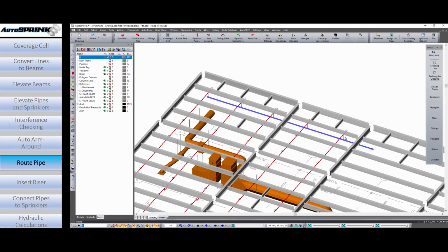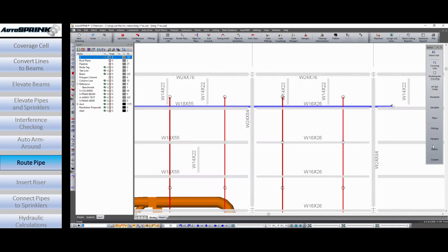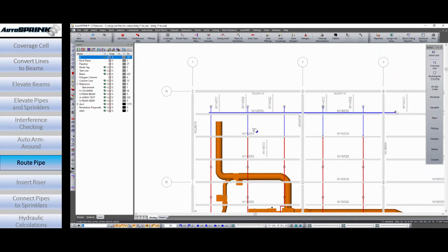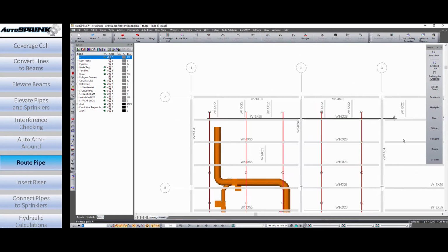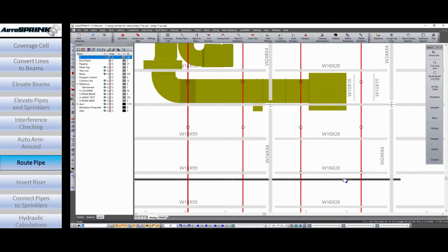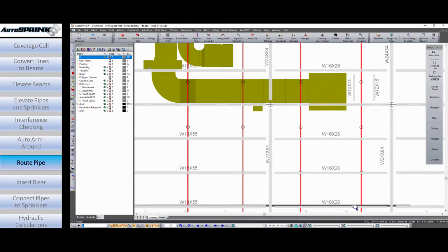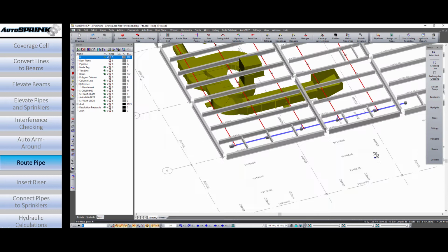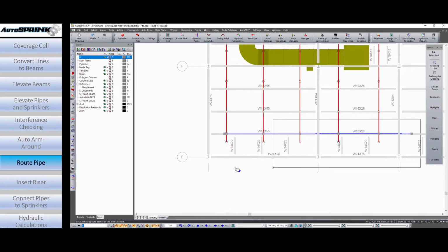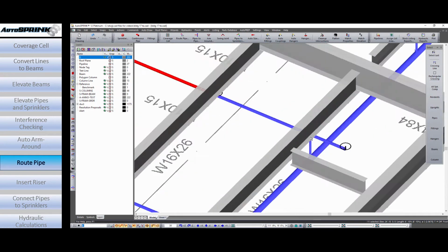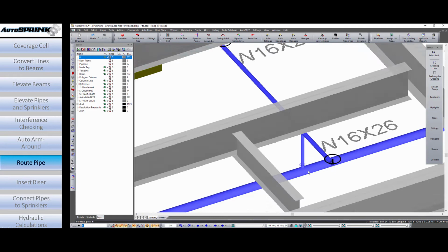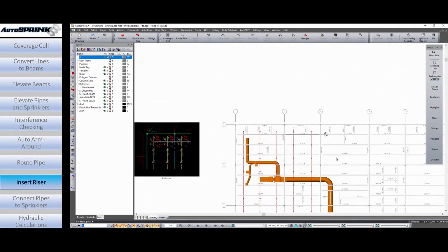So when I flip to ISO here, you'll see the riser nipples are already in there, and I'll grab all that piping and clean up intersections, make sure I've got proper outlets and branch lines broken at the tops of riser nipples. Now I'll use a selection filter to grab only pipe, which in this case will be riser nipples and cross main, and I'm going to copy that down to the bottom of the page and put in my floater main. So we'll grid these 5 branch lines. And if I zoom in here, you can see you need to run clean up intersections real quick, make sure those connections are right, and then zoom in, you'll see the outlets and see the proper connections there.